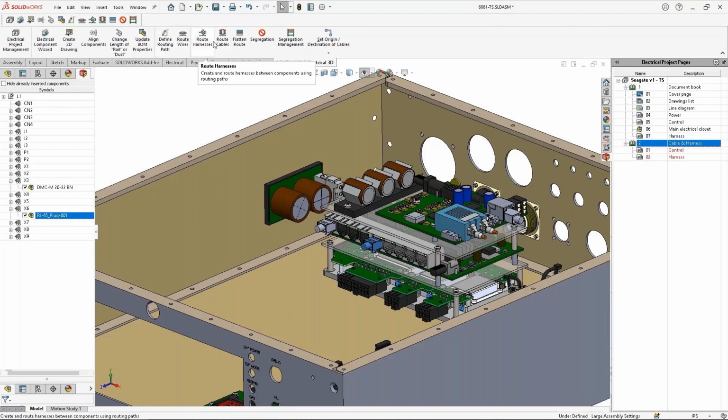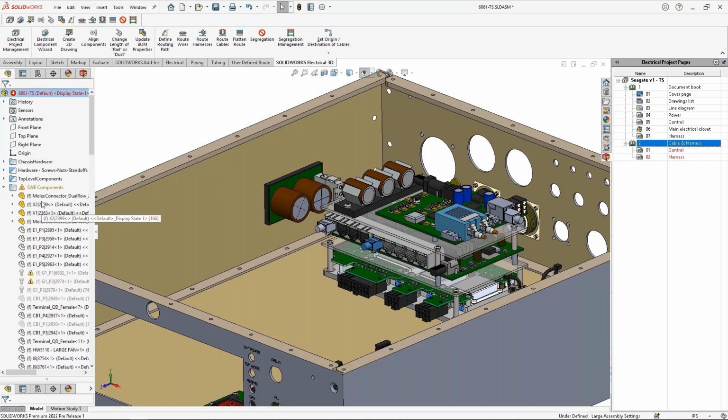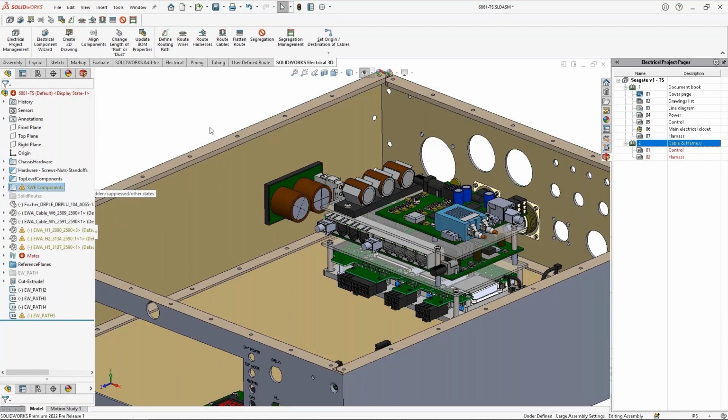Here on the electrical tab, because we have the integrated environment, I have tools or access to a lot of electrical information. Notice that in some of these connectors and models, in the front of their model name, they also consumed the component tag. And I think that's great when it comes to documenting. Now, real quick, before I route this, I want you to know that I did define a generic path that these will find. It's not a detailed path, it's just a generic route that I want the wires to follow. Then based off of their defined wire properties, they will follow as such.